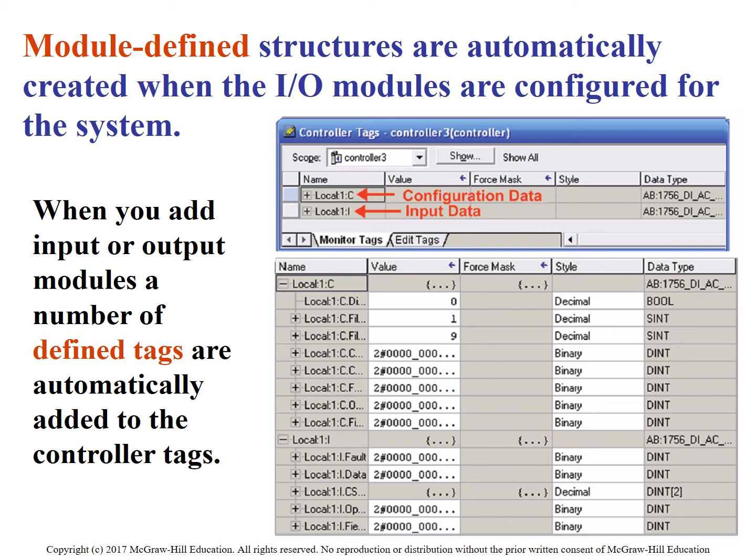Module defined bits. Again, when we actually open up that software for the ControlLogix L16ER, we notice how it automatically populates the inputs and outputs for us, because what? It's a fixed I/O unit, so it already knows how many inputs and outputs it has. We don't have any additional configuration associated with it like we would here, where we have a modular solution where they've got to incorporate individual slots for each input and output.